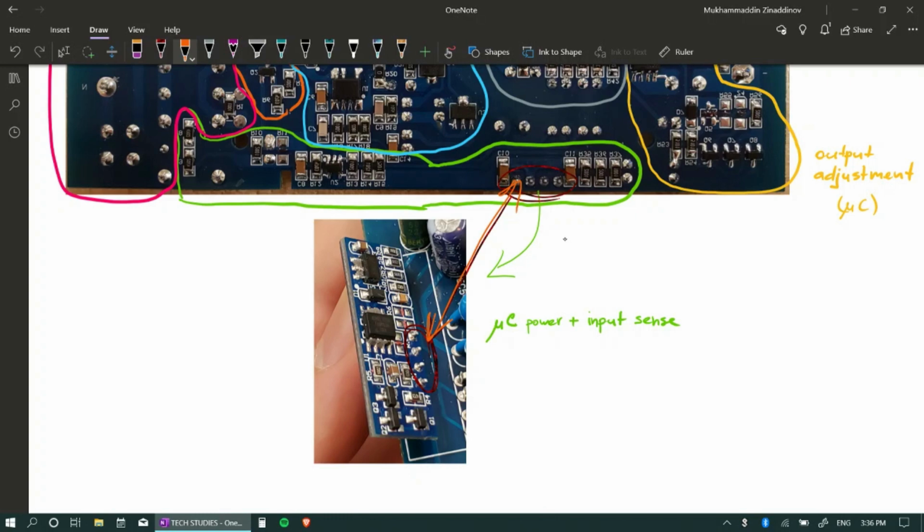That is to avoid crosstalk and electromagnetic mutual pollution of the signals, because if the digital part of the circuit is affecting the sense input, then of course the microcontroller's decisions based on that input will be affecting the output, and then the entire purpose of sensing and adjusting the output will be counterproductive. So in this case, they chose to separate the digital part of the circuit to another PCB, and they just connected it with pins. It also serves a second purpose of saving space.